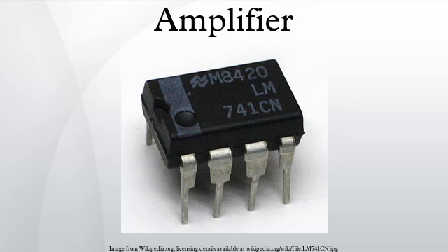Inefficiency comes from the standing current that must be roughly half the maximum output current, and a large part of the power supply voltage is present across the output device at low signal levels. If high output power is needed from a Class A circuit, the power supply and accompanying heat become significant. For every watt delivered to the load, the amplifier itself, at best, uses an extra watt. For high-power amplifiers this means very large and expensive power supplies and heat sinks.